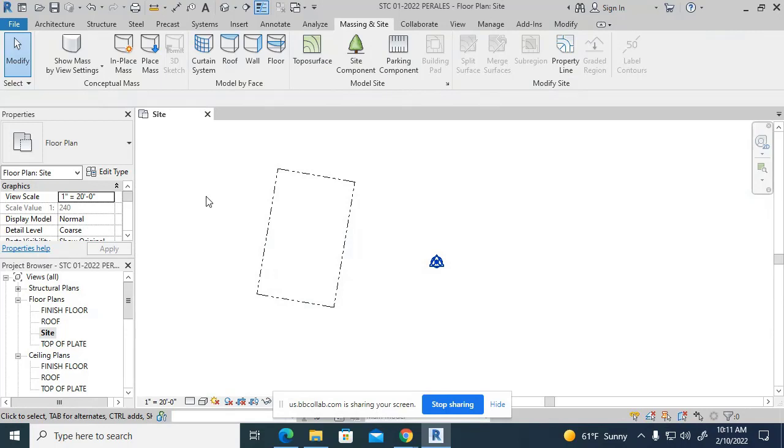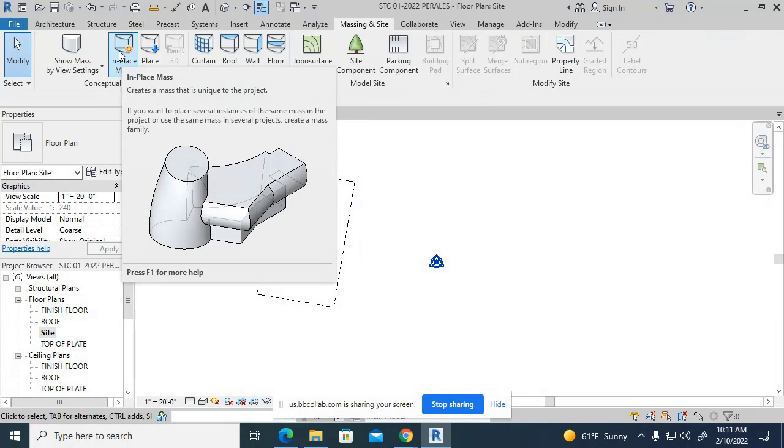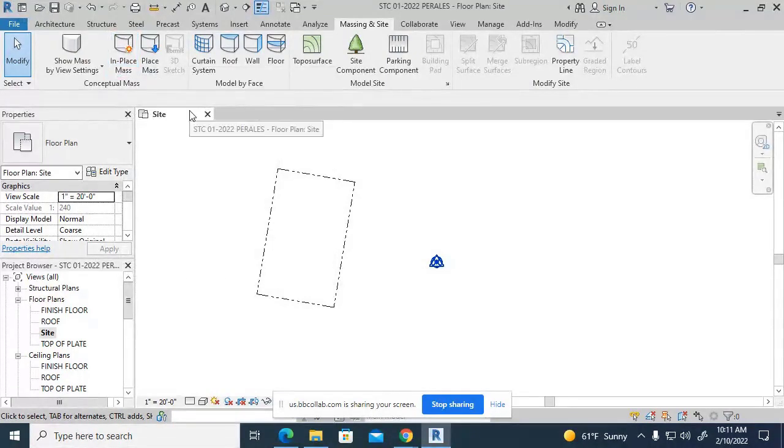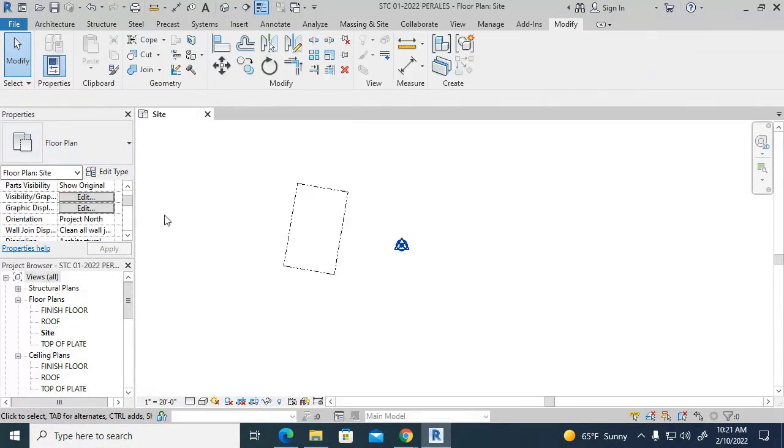Mr. Reyes, this looks all crooked. I know. That's how the land is out there. Okay. This is what is termed true north. This is how the lot is actually there. Now, you could print this like this with the site plan at an angle. The problem is that your house is then going to be vertical. It's a lot harder to turn the house to meet the site. It's a lot easier to turn the site to meet the house.